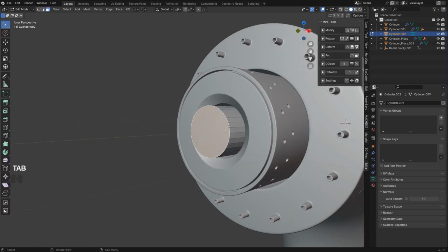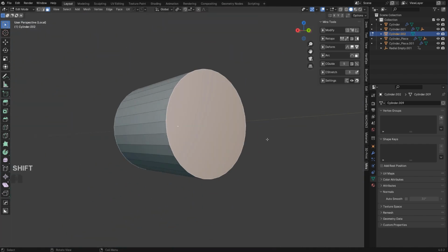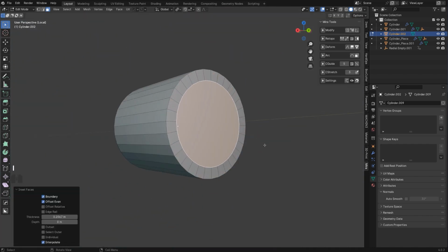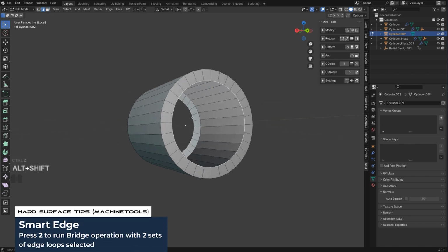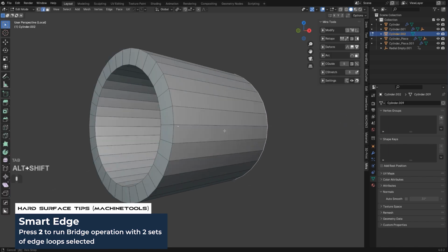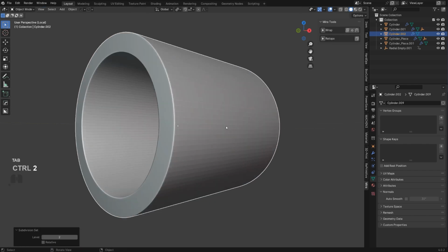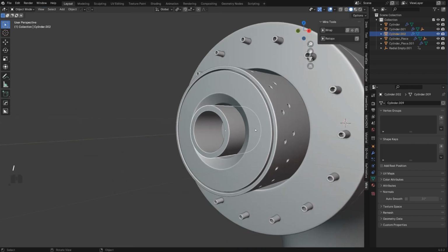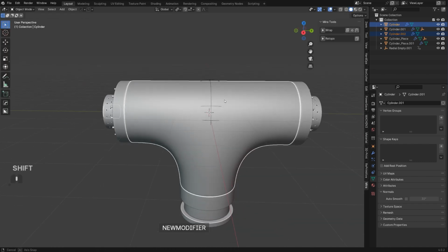Let's grab both of these, and we're gonna inset them like this, and remove the faces, grab these 2, press 2 to merge them, and then select all these edges, create a really tight chamfer, and Control 2 and shade smooth, and you're done. And we got this, and we're looking pretty peachy, right?